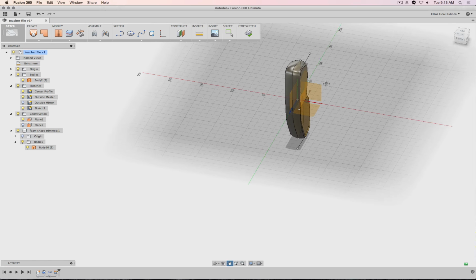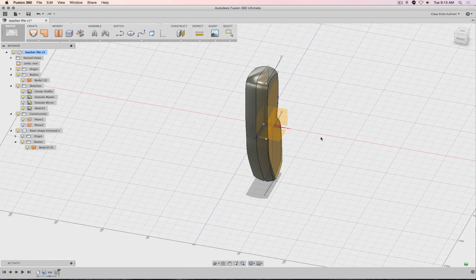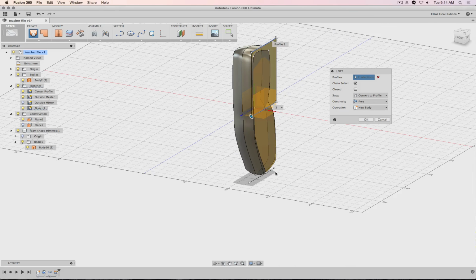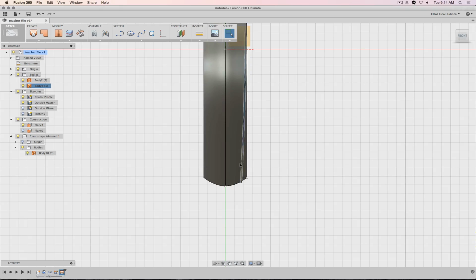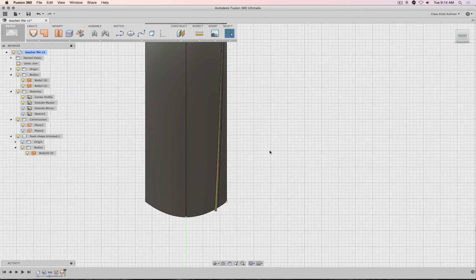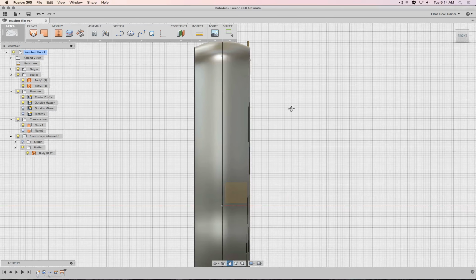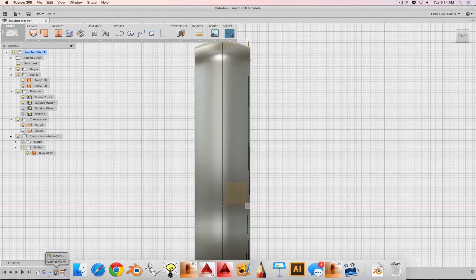Perfect. So then stop. And now those 3 splines I created, I'm going to loft. So number 1, 2, and there is 3. Okay, let's take a look if and how I'm hitting the original design. Not very close. That is also fine because those lines I created are slightly somewhere else.